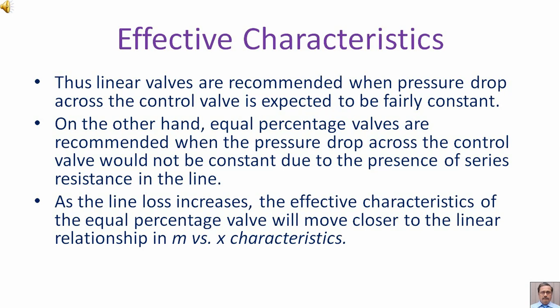As the line loss increases, the effective characteristics of the equal percentage valve will move closer to the linear relationship in M versus X characteristics.